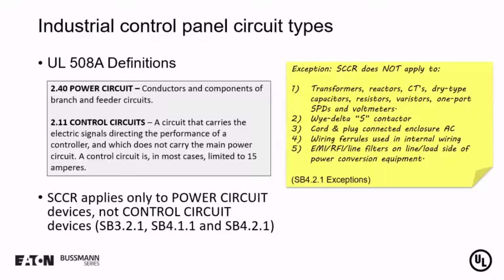Before we get into the requirements of UL 508A supplement SB and determining the SCCR of an assembly, it's very important to start with the definitions. So I'm going to cover the key definitions that will pertain later in the presentation when it comes to analyzing your panel for SCCR. The first thing, we kind of talked about this before, is that we have power circuits and we have control circuits. And when it comes to SCCR, only the power circuit devices affect the assembly SCCR. We don't worry about the control circuit components.